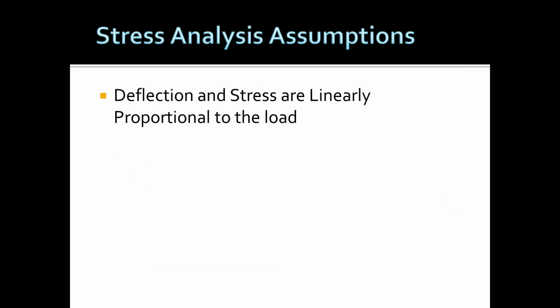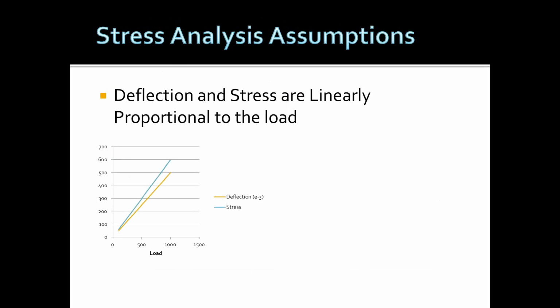So to talk about the stress analysis, there are some assumptions you need to make when you're using Inventor Pro to work with your stress analysis. Those assumptions start with the deflection and the stress are linear. The analysis that Inventor does is linear only. What does that mean? A lot of people may not realize what the linear loading means. So as you apply a load, there's a particular amount of deflection or deformation or movement in the product.